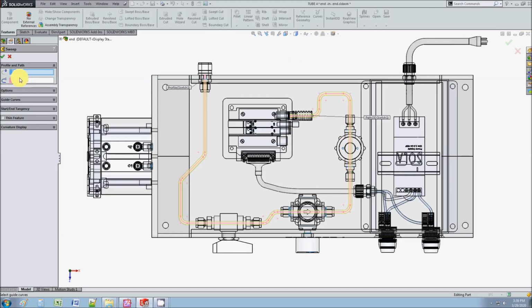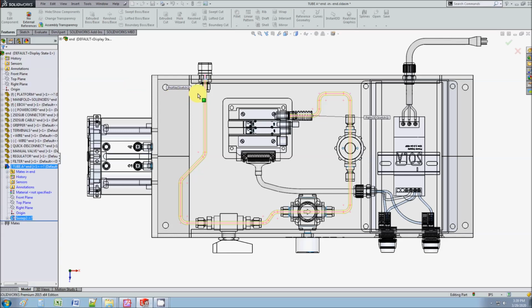And again, like I said, in the newer versions of SolidWorks, if you need to sweep a pipe, you don't need a circle. You can just select circular feature and specify a diameter. I think that was in version 2018 or something like that where that came out. But if you're using something earlier, you've got to select both. You click OK, and there's the result.